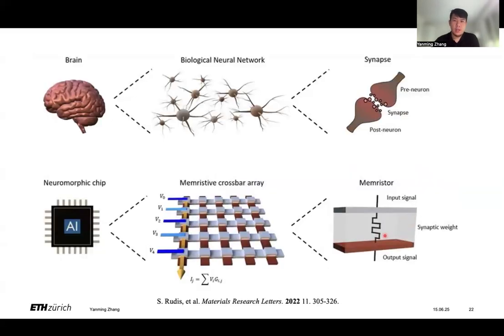If we go back to this slide, from the application point of view, in the crossbar array of memristors, we compute the vector matrix multiplication, and we want to store this synaptic weight in multi-level memory by the conductance of the device. For this reason, we wanted to see if we can program the synaptic weight in different conductance levels of a single device.